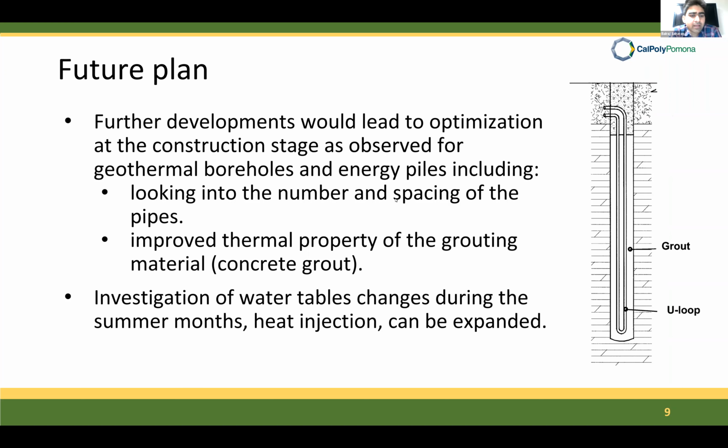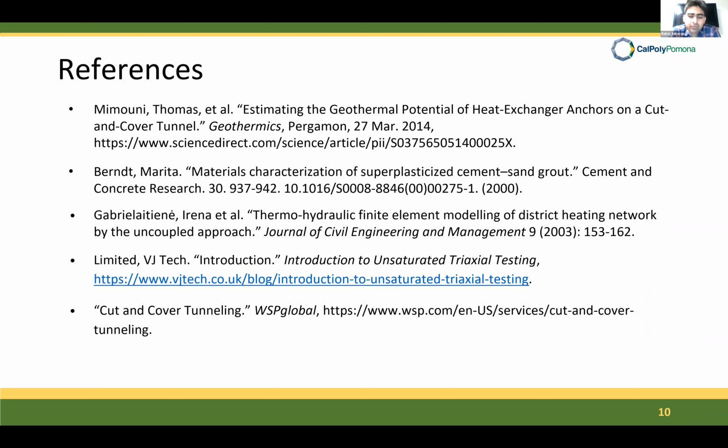So for future plans, we are looking to optimize the number and spacing between the pipes, and also to improve the thermal property of the grouting material for concrete grout. And we are also investigating the water table changes during the summer months for the heat injection part.